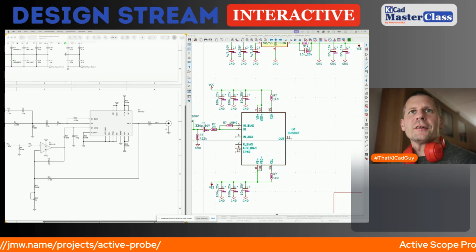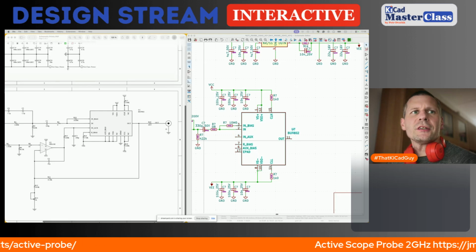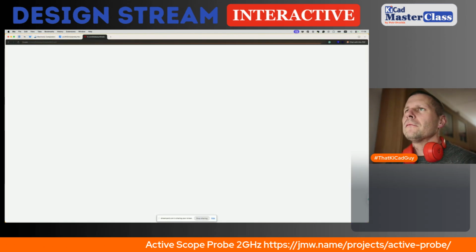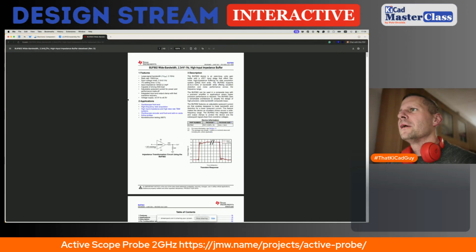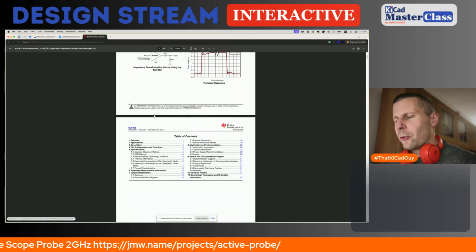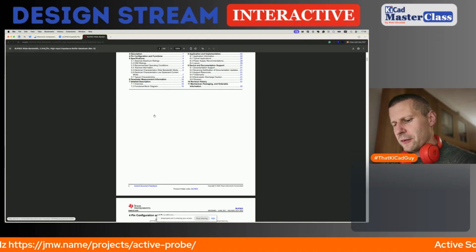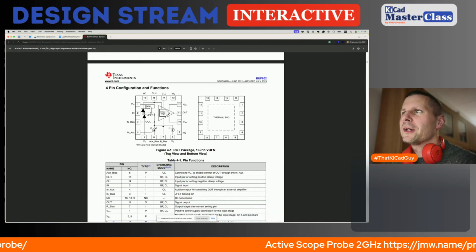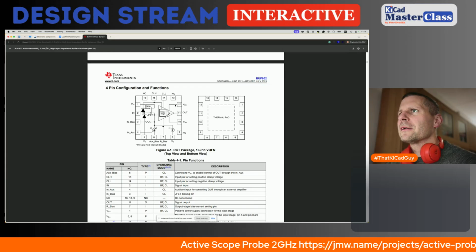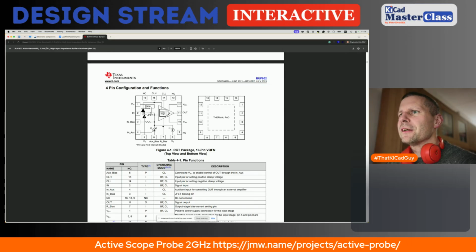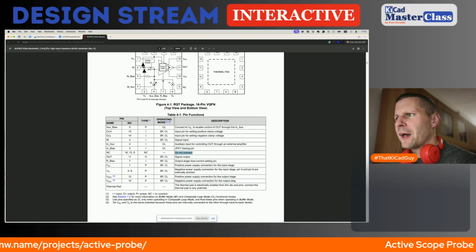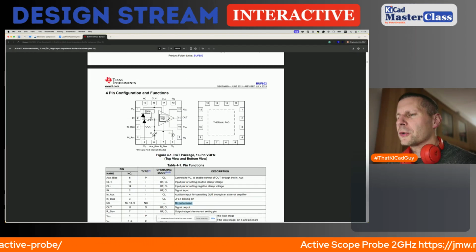Yeah, we need the data sheet. Here is the link, and we are looking for the non-connected ports of the symbol or package. Number 9, 13, 16 are not connected. They say do not connect, and I will not.